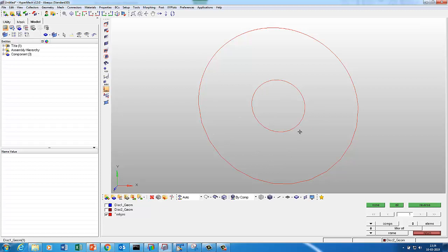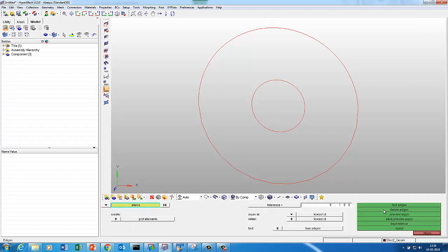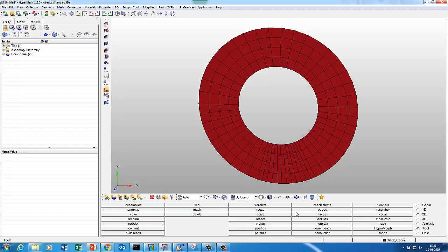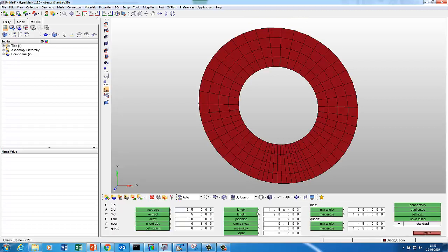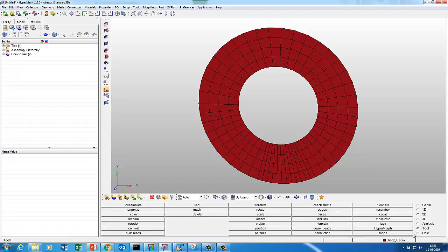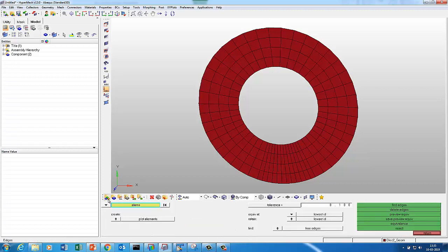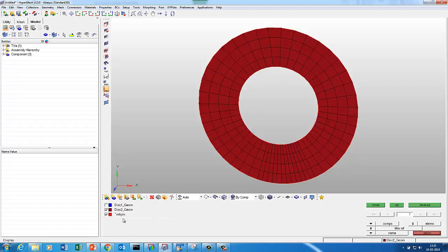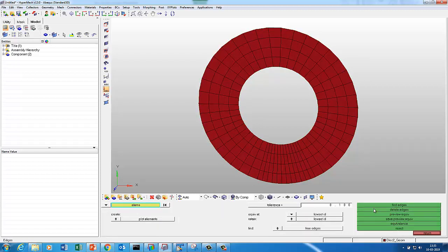So you might get just the outer feature of that, so there is no issue, it's perfectly merged and you get the outer finish. So delete the edge. Now you put the second one, again go to tool, check element, check the length, it is 0.3, and again you can go up to 0.3. So element display preview equivalence, so done, find edge, and then you get outer, so it's perfectly fine. So Shift F3 and I'll delete the edge.